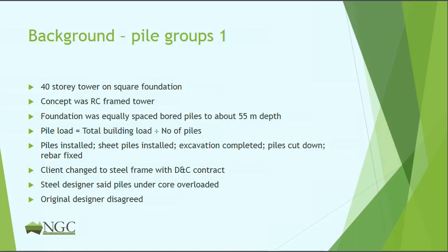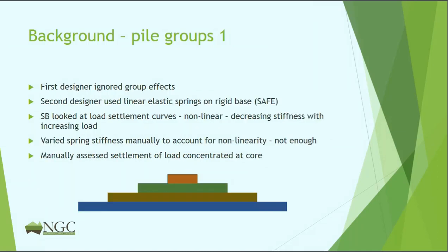When I analyze the loads coming down the core, the piles under that foundation that's already in the ground are overloaded. And the original designer said, don't talk BS. I designed these piles for an RC frame structure, which is obviously much heavier than a steel frame structure. Of course they're all right. And I was called in to referee in this dispute.